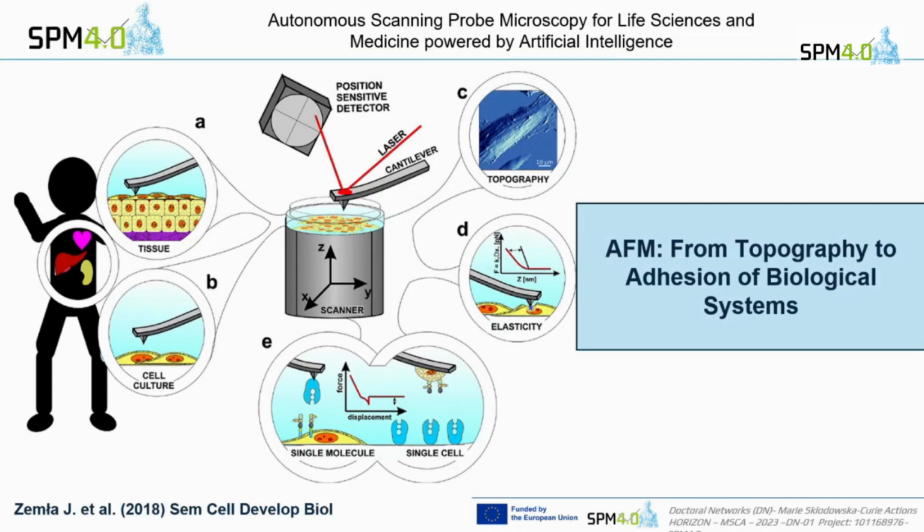And this relation between the gap and the diameter also has to be checked versus the sample you are probing. If you have very large particles, for example, if you're measuring a suspension with very large microparticles, then from the size of the microparticles, you have to validate. It's the same as with probe resolution. So there is some limit for, let's say, rheometer measurement resolution.